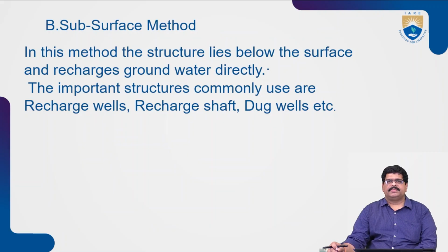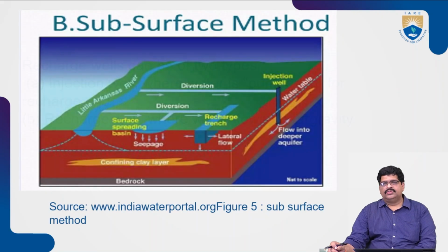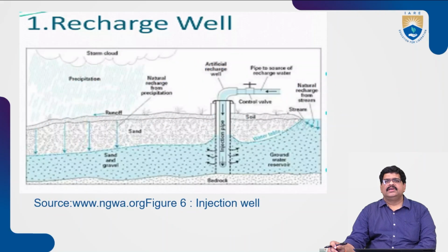Next, the subsurface method. In this method, the structure lies between the surface and the groundwater and recharges the groundwater directly. The important structures commonly used are recharge shafts or dug wells. So these are the recharge wells. Let us see that one.